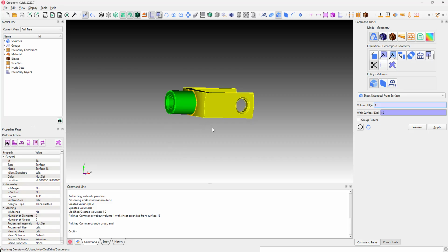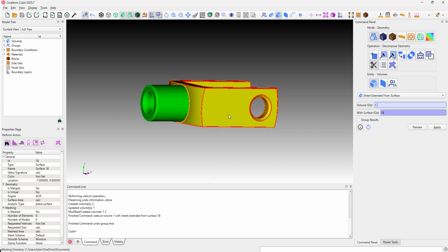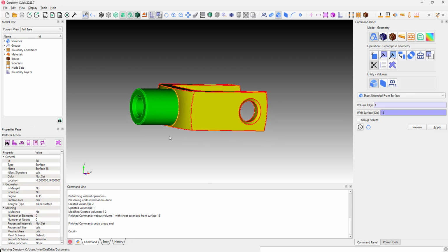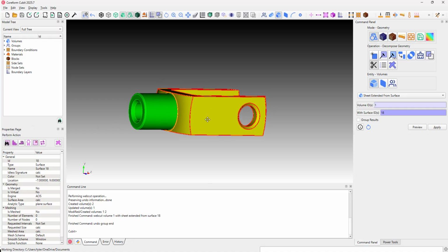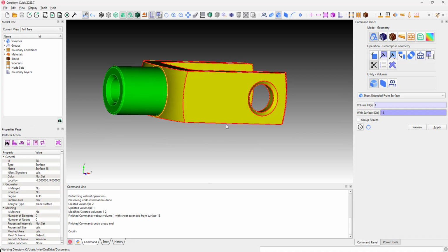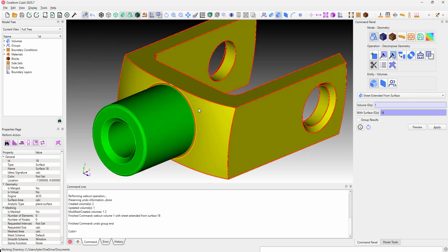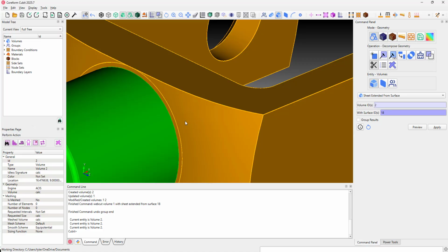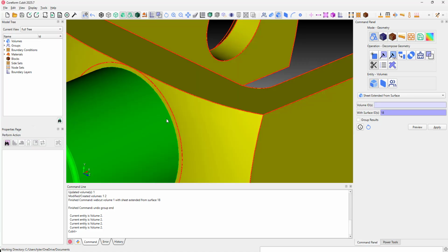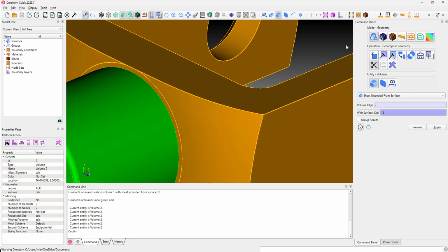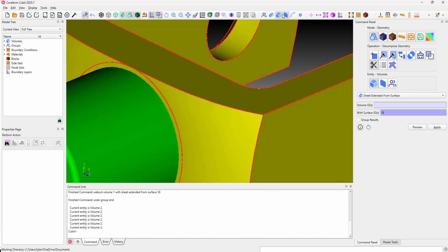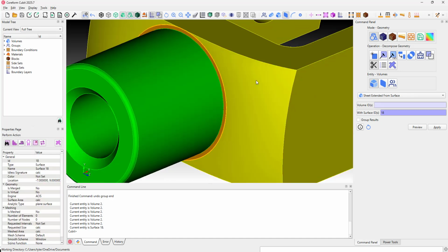Now we will return to removing or fixing the small features or surfaces we've recognized. I recognize about 5 possible issues that we need to address to get the best mesh quality. So, let's start by removing the small circle surface right here.